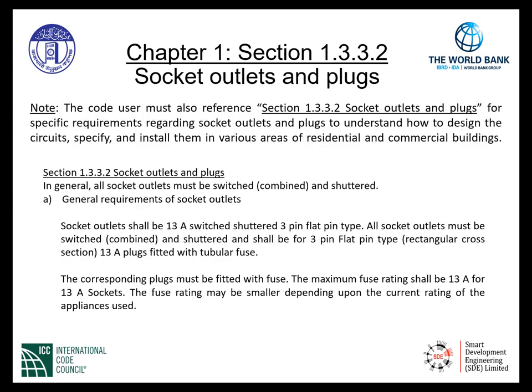Note, the code user must also reference Section 1.3.3.2, socket outlets and plugs, for specific requirements regarding socket outlets and plugs to understand how to design the circuits, specify, and install them in various areas of residential and commercial buildings. In Section 1.3.3.2, in general, all socket outlets must be switched, combined, and shuttered.